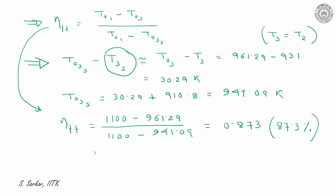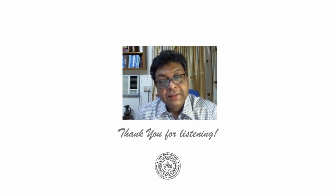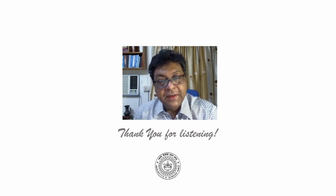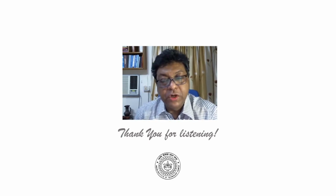Thus, one can see eta total to total is greater than eta total to static. I have solved an illustrative example for a gas turbine and evaluated eta total to total and eta total to static. And through this example, I have also indicated that eta total to total is higher than eta total to static.